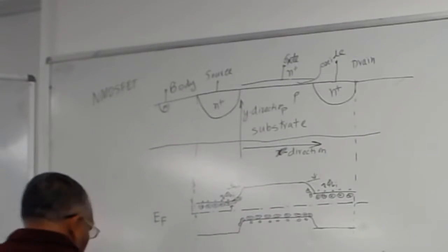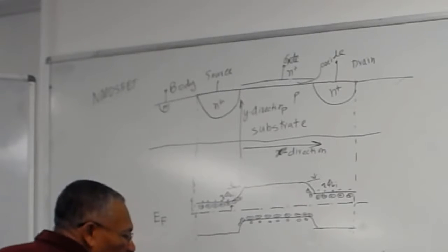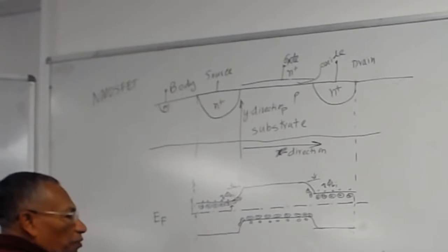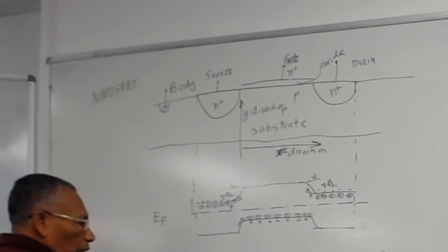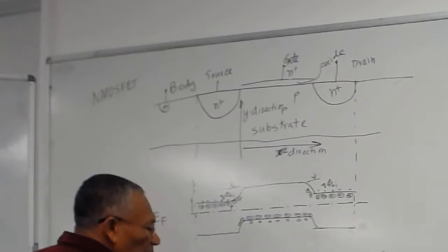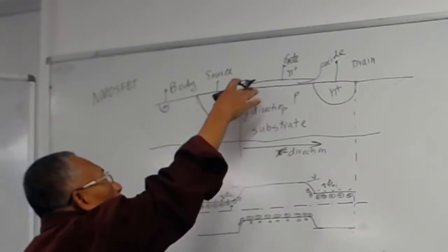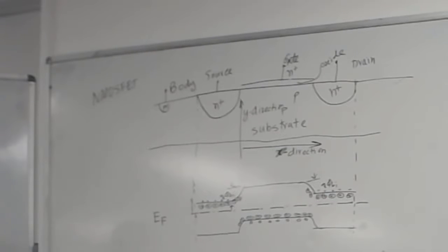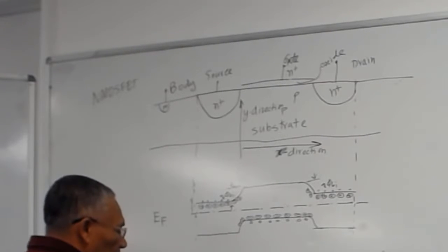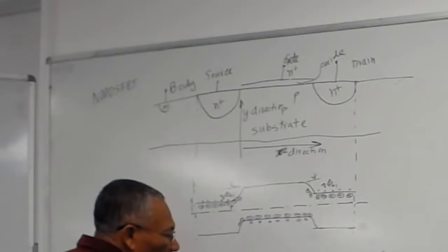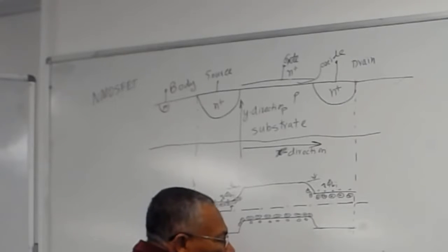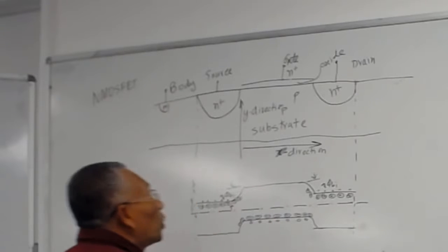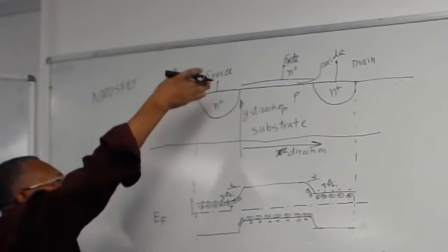So how to draw it? You can first draw a p-n junction and separate it, or if you're confident, you can draw in one stroke. Here you see, this is in equilibrium because you haven't applied any voltage, so everything is in equilibrium. You can first draw your Fermi energy level like this. EF, Y, because I'm showing the Fermi energy level for the Y direction.